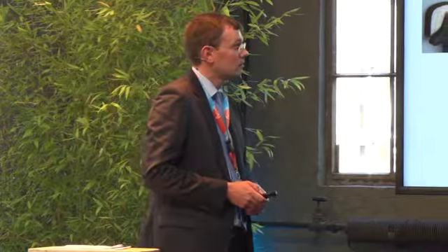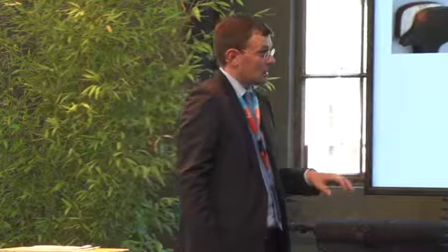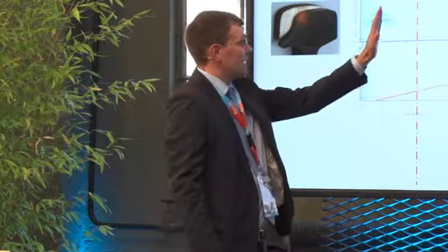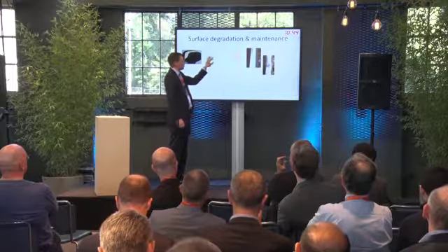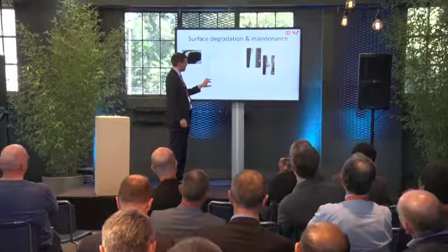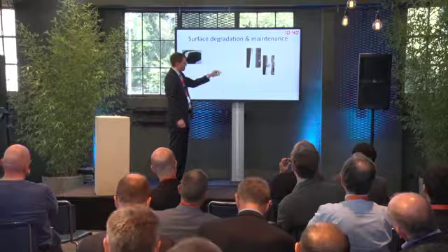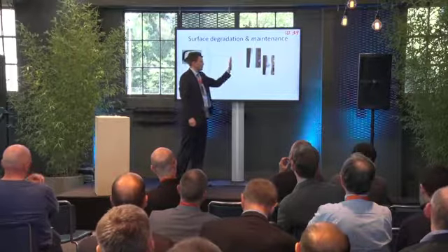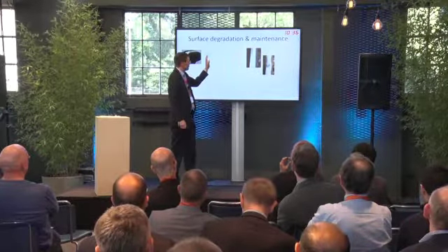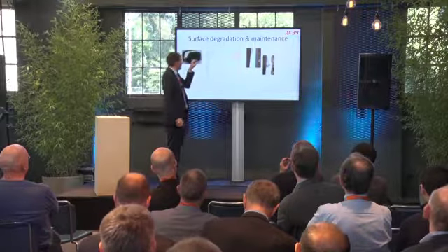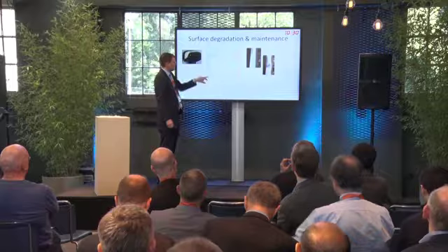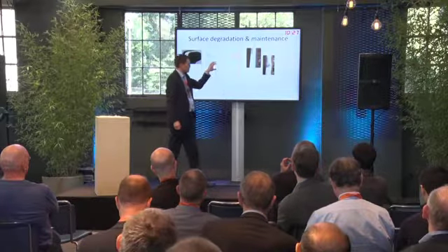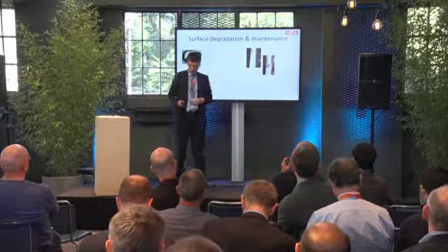Of course, this has consequences out in the field. When we look again at this graph, at the left we have a typical degradation regime, which is wear. So the softer the rail, the higher the wear. And at the right, we are moving into the RCF degradation regime. So here are some illustrations. This is the typical behavior at the left side in this chart, and this is the typical behavior that we find at the right side.